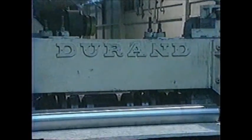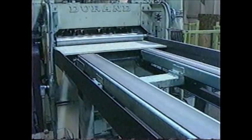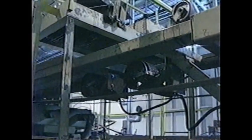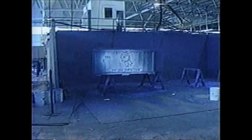Georgia-Pacific Sturdi-Floor, for example, has tongue and groove edges. The tongue and groove help maintain a level surface at panel edges when panels are used as underlayment. After sanding, the graded panels pass over an APA grading wheel, which prints the appropriate information on each panel. Some panels have their edges sealed for protection against moisture. In one of the last production steps, the Georgia-Pacific logo is stenciled on the package of panels, and the package is then wrapped.